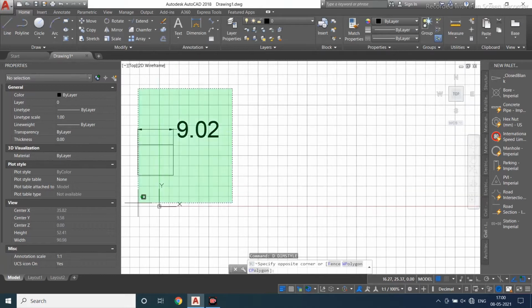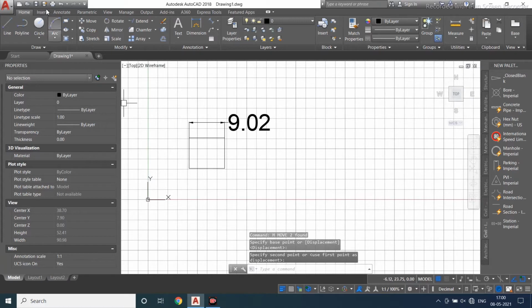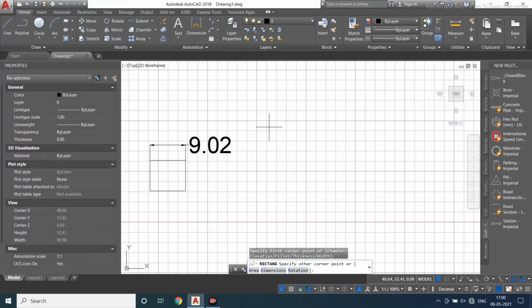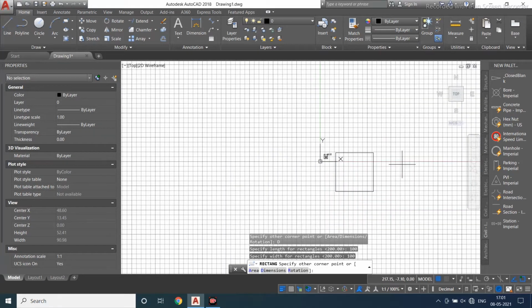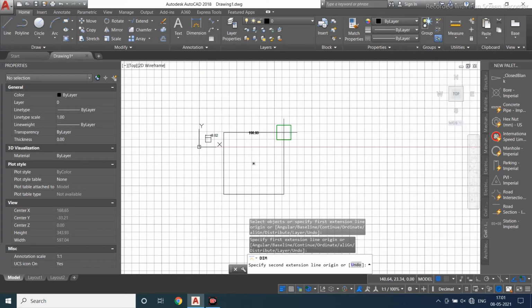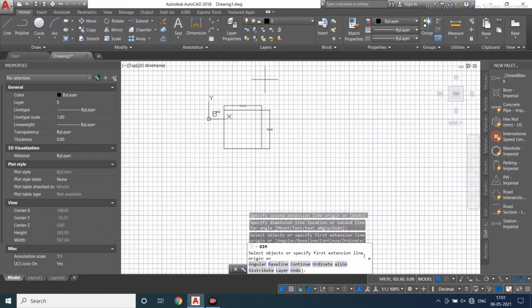This is nominal enough. Then you can move it. Now here, the rectangle, I'll be selecting here. I'll give it directly with a measurement. Specify a base point, then go for a dimension in your command panel and enter how much you want. Suppose I want 100, enter. Width, how much do you want? 100, enter. So you got a 100 by 100 rectangle. If you want to check, go for annotation and take a quick measurement, so you'll know whether what you have done is right or wrong.